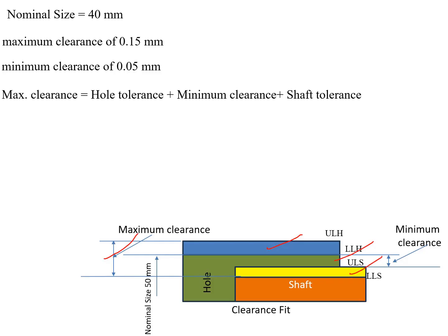In the data it is given that the maximum clearance equals 0.15 mm, and the hole tolerance equals 1.5 times the shaft tolerance.